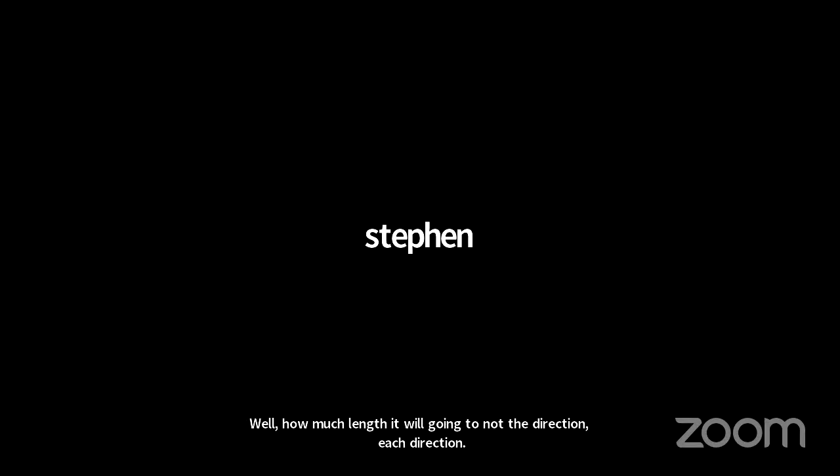What do we need, 3D modeling or is isometric sufficient? Isometric is sufficient, because we need to know the length, how much length it goes in the north direction and east direction. That is enough for 3D modeling. No need to go to GA drawings. We need the piping material specification, PMS, because we need to check the thickness from that. 1 mm will affect the pipeline during construction, and in real time it is not possible to save 1 mm.